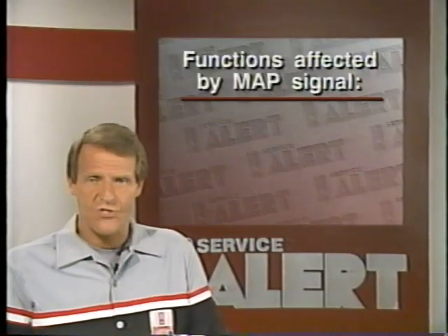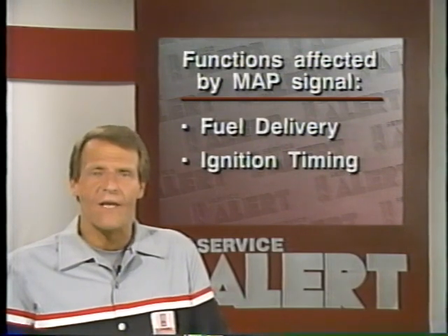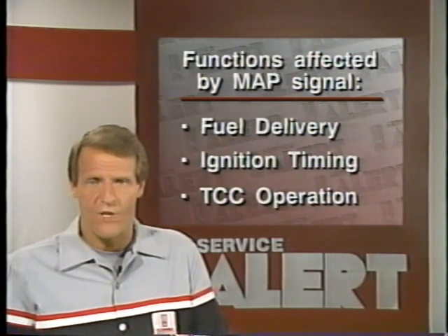Each time it gets a voltage, it checks that value against a lookup table. That's a set of values stored in the PCM's read-only memory, or ROM. Using this table, the PCM calculates the load on the engine. The PCM then factors engine load into its calculations for fuel delivery, ignition timing, and torque converter clutch operation.